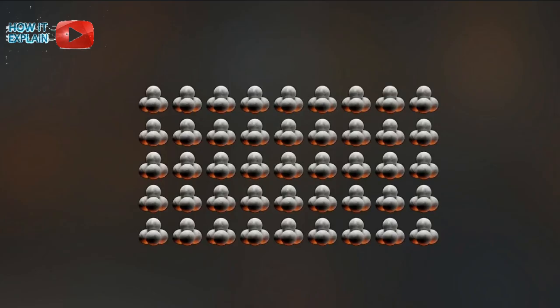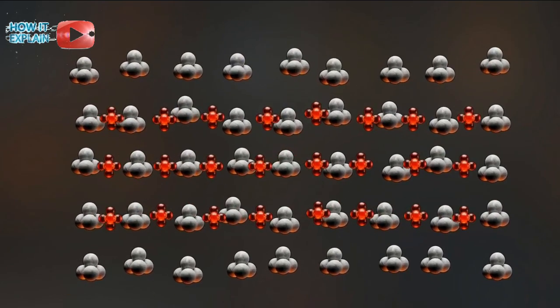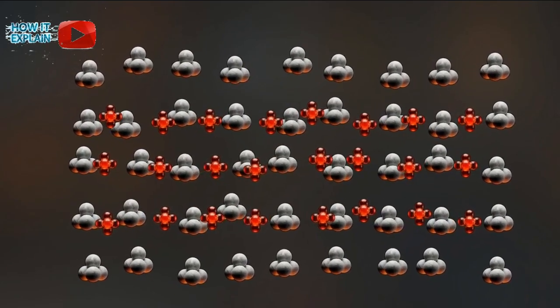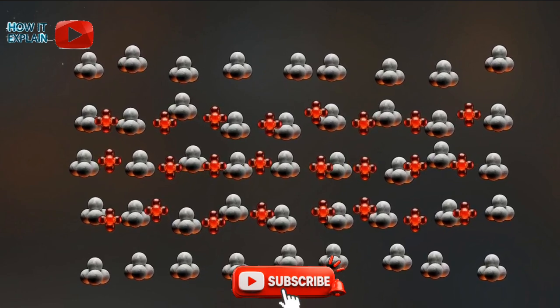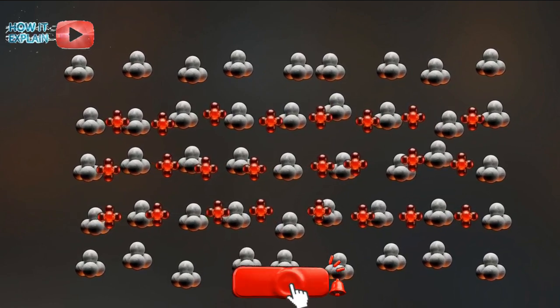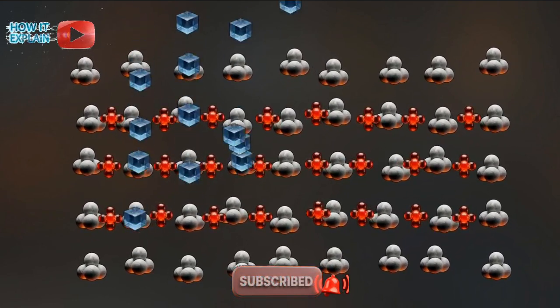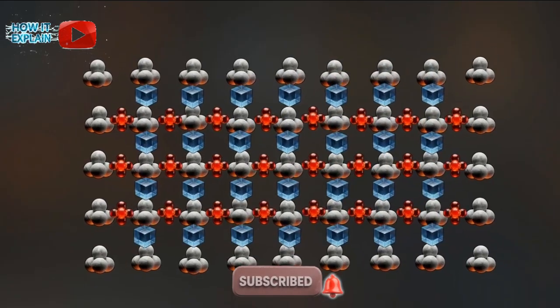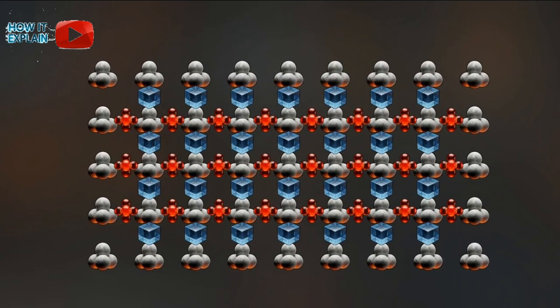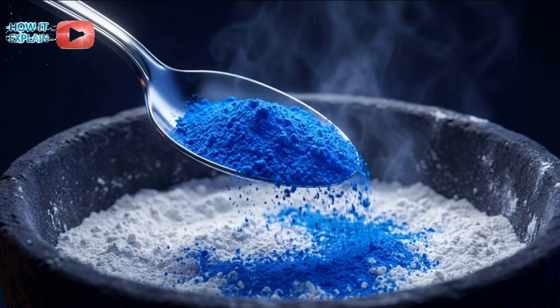Silica has a high melting point, so engineers add sodium carbonate. This lowers the temperature threshold required for the sand to liquefy. However, sodium makes the glass water-soluble. Adding calcium carbonate stabilizes the structure, giving the material its permanent durability. This is also the stage where color is introduced. A small amount of cobalt oxide can dye the entire batch a deep blue.